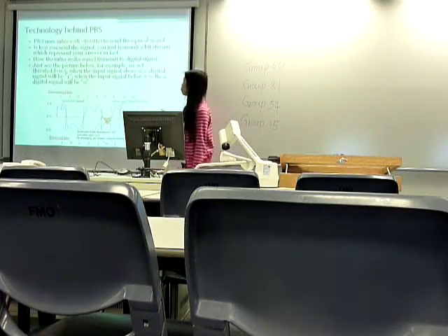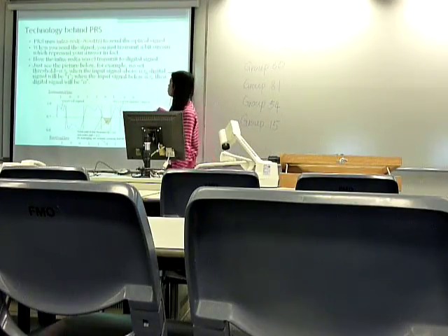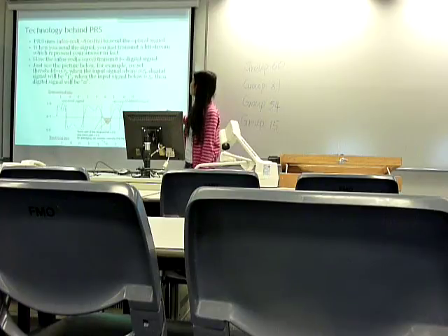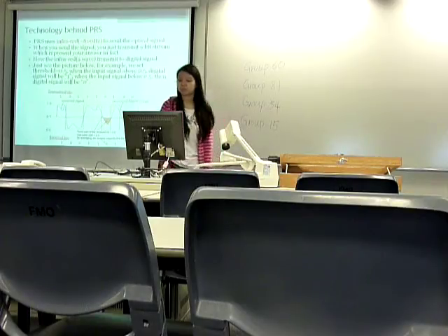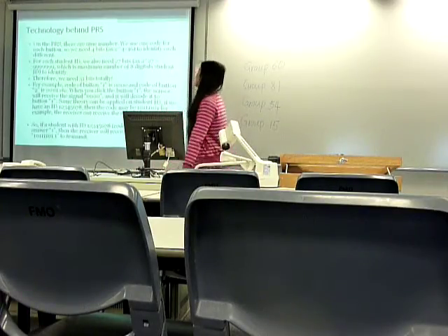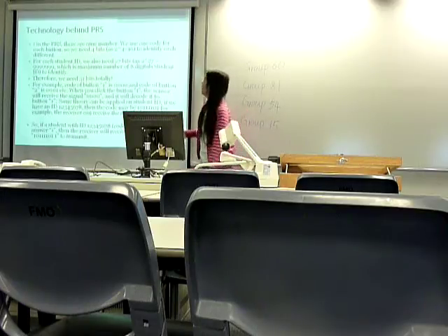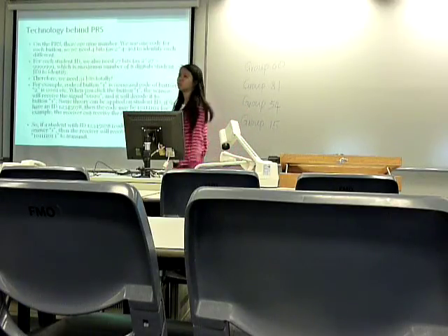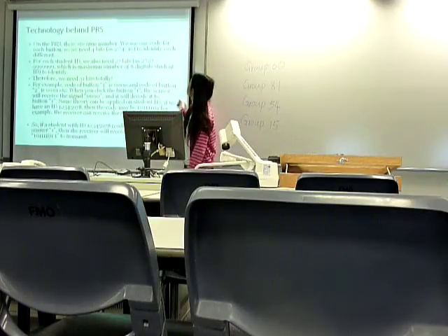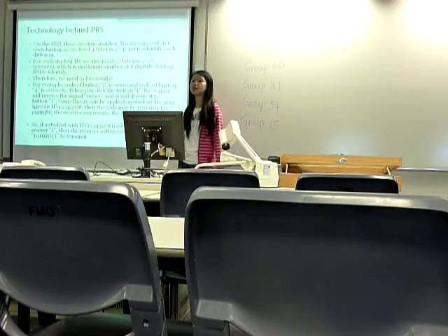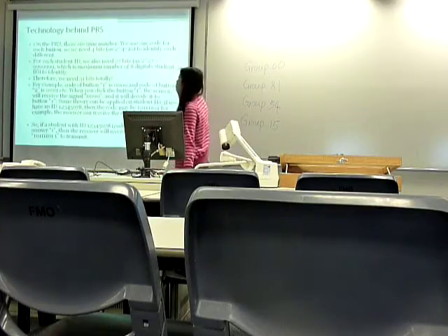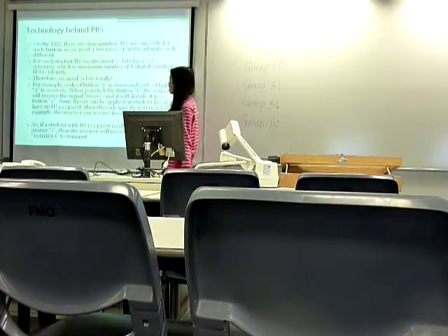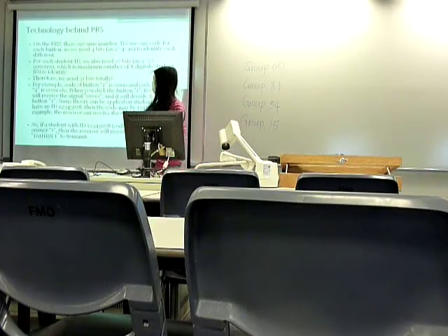So first, the infrared signal is like this. If we transform it to the digital signal, we will have this kind of digital sequence. And then on the PRS, there are 9 numbers on it. So first, we use one code for each button, so we need 4 bits to identify. And since we also use the student ID to identify each PRS, we also need 27 bits to identify the students, and therefore we need 31 bits in total.